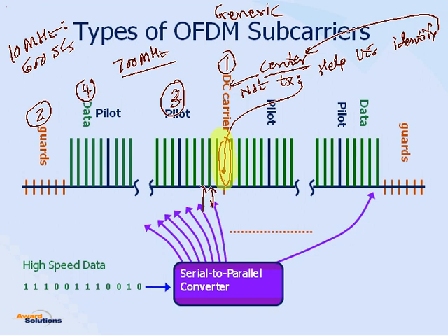So you are looking here, you are looking here, yeah? You are looking around 700 megahertz. So around 700 megahertz, wherever you find minimum energy, that's where your center is. Okay. So DC will help you identify the center of the spectrum.